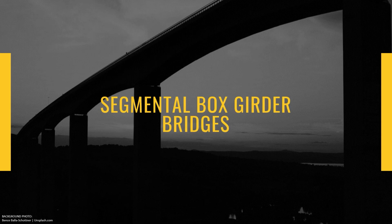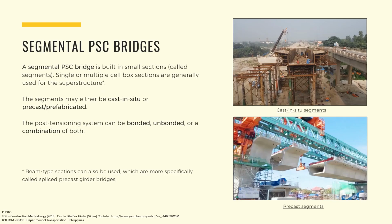Now, we'll be talking about segmental box girder bridges. By definition, segmental bridges are bridges that are built via combining sections, called segments. For segmental PSC bridges, single or multiple cell box girder sections are generally used. The box girder segments may either be cast in situ or precast off-site. For the post-tensioning system, they can either be bonded, unbonded, or a combination of both.